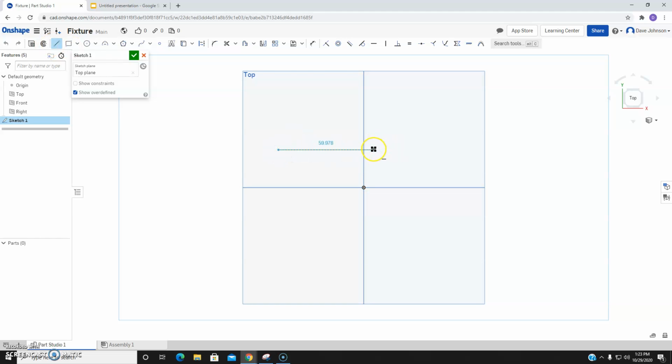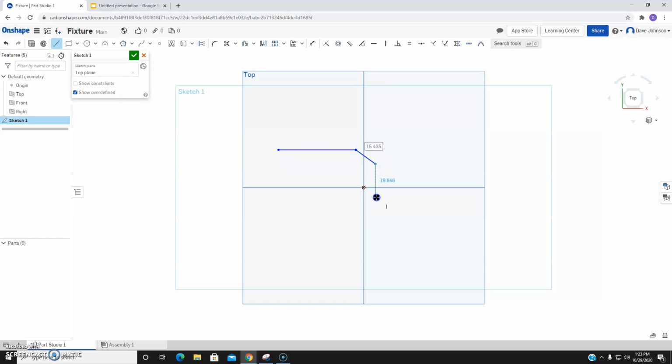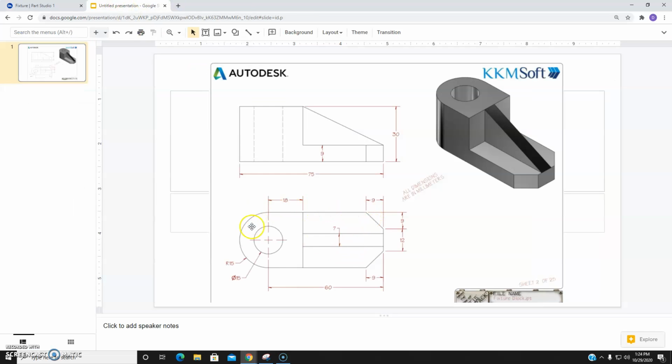You can just sort of rough out this shape. It doesn't have to be particularly accurate, but I'm going to get it close. Add our little chamfer here. Now you'll notice as I go near the center point here, it is trying to lock onto that. We don't want to lock onto that, so we'll just kind of leave that alone. Kind of hover, kind of connect to that there. I'm just going to temporarily draw a line across here so we can add in our circle, and then we'll just trim things up later on. So we'll lock that in, and we'll hit M. We'll trim that away, and trim these 2 chunks away. So we've got, again, our basic shape of just the outside base here.